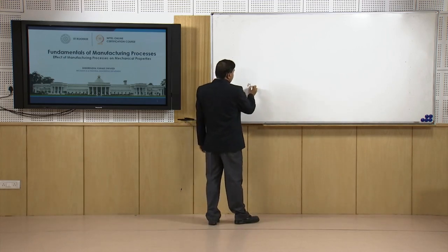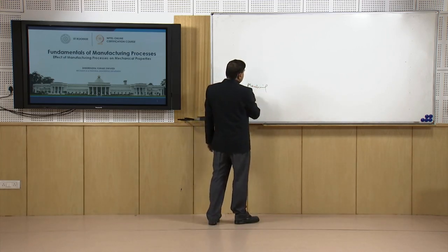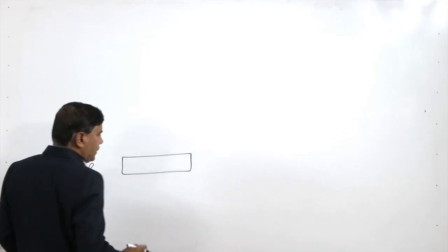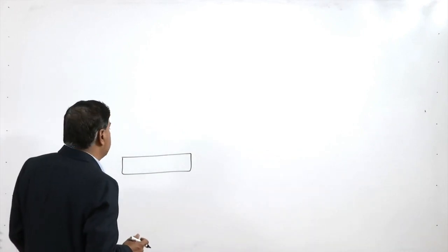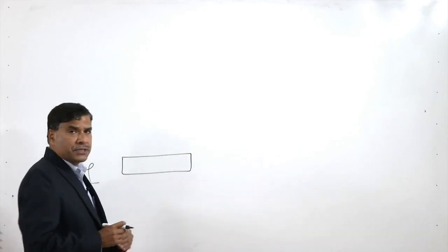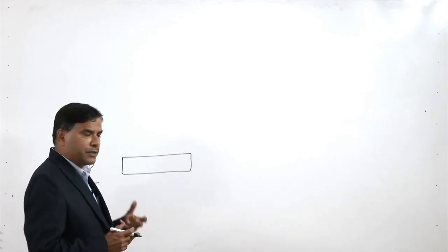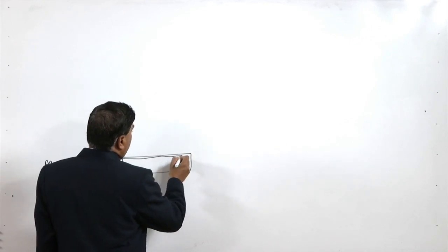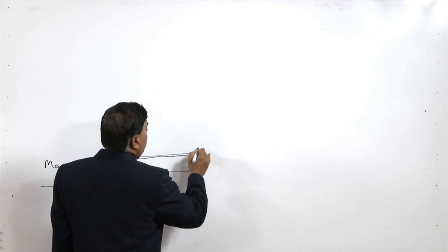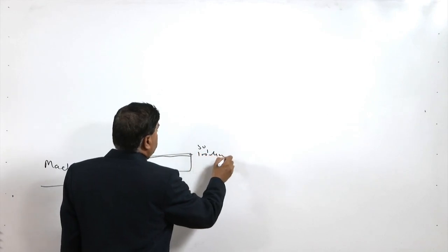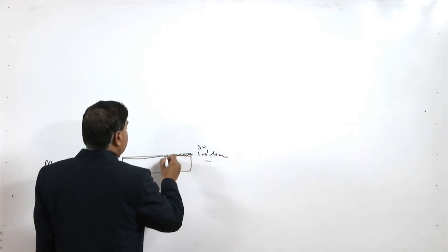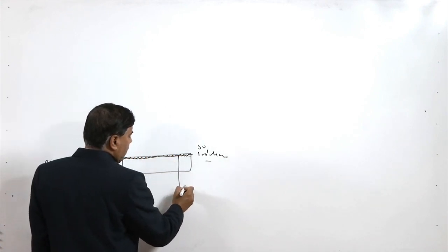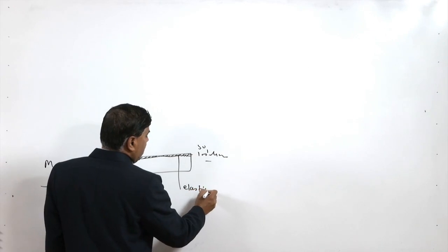Then we have the machining. In case of machining, very near surface layers, in those mechanical machining processes where shear force is used, or a shear mechanism is involved for removal of the material, a very thin layer of say 50 to 100 micrometer is left at the surface after removal of the material in the form of chips, and this layer is primarily elastically deformed.